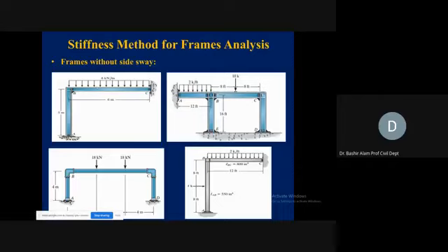So the left top diagram I'm discussing now, if you look at the support conditions, these are enough to tell you that it is not allowing any sway, without looking at the load or other geometry of this problem. Now coming to the right top, if you see here again at A, which is this left top support, again we have a hinge support.